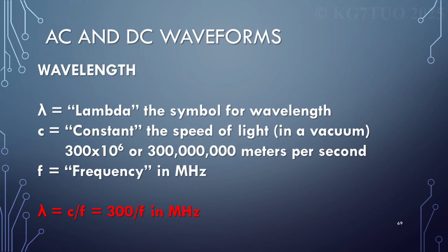The antenna that you need. Well, okay. How long you cut your elements. Right. Yeah, every frequency requires a different length of element, but you can get a wide section of a spectrum with one length of an element. So wavelength is measured in meters? Yes, the wavelength is. So you need a certain length of your antenna. We will cover it in depth, but yeah, you cut your antenna, if you're building your own, to the length that the wavelength you're going to operate on requires.